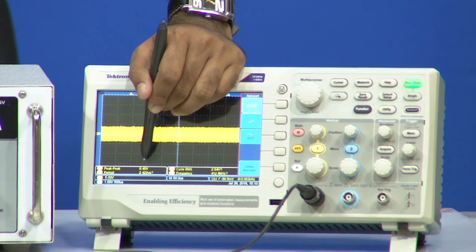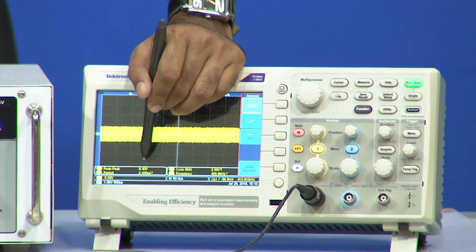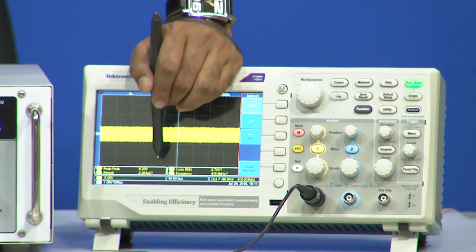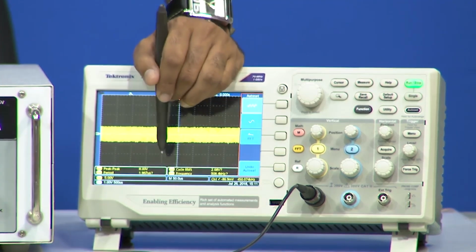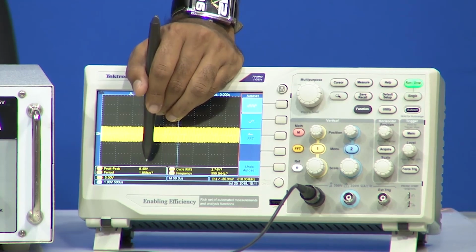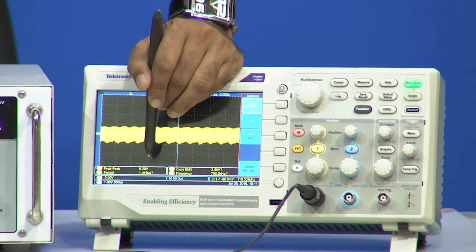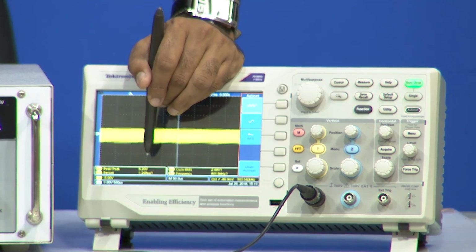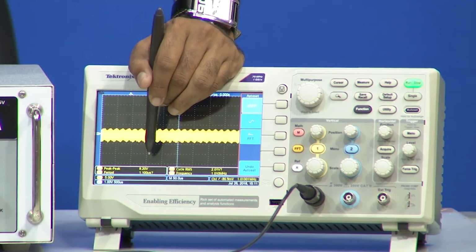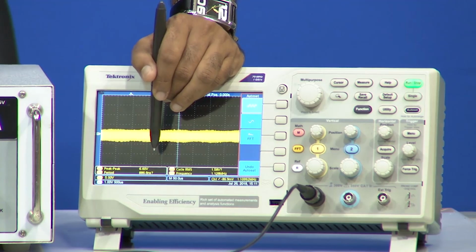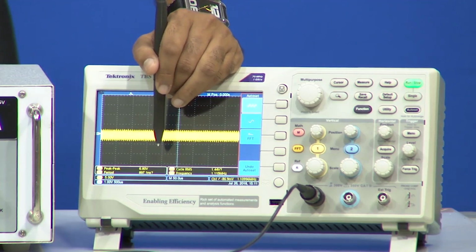For the other circuit at 400 kilohertz, we saw the output coming down considerably, from 16 volt peak to peak to 12 volt peak to peak. But here it is remaining constant. You see the difference. At 510 kilohertz, still constant. See, it's 8.2 volt. 610 kilohertz, 710, 810, 910 kilohertz, still constant. 1 megahertz, constant. At 1.1 megahertz, now it is slightly decreasing. Now it will slowly decrease.